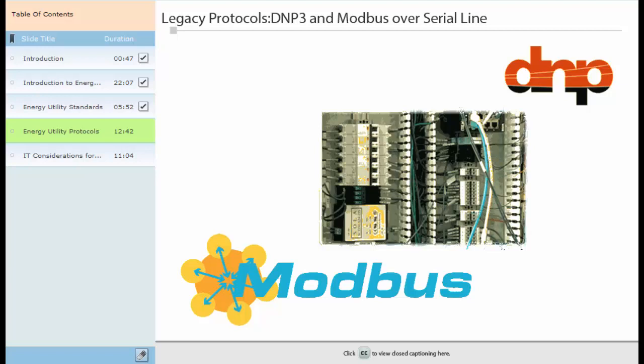The message can include any amount of application data, even 0, if the command is transmitted. Originally, the physical layer of DNP3 transmitting could be implemented by means of RS-232 if short-distance point-to-point communications were required, RS-422, which represents a bidirectional extension of RS-232 for industrial networks, or RS-485 if multi-point communications were needed.